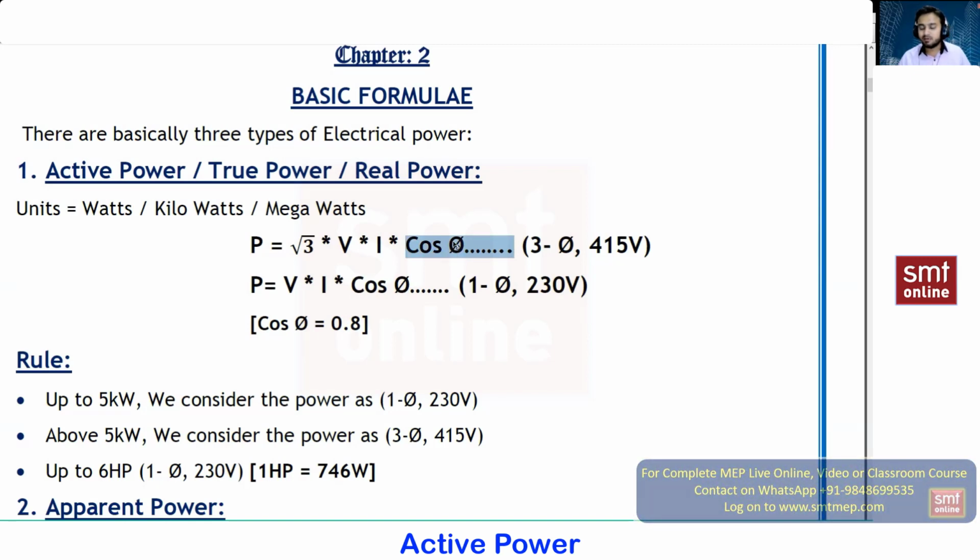This is the basic power factor value which we get from the substation. In my course, I'm going with a power factor of 0.8. If you're working in a metropolitan city, or on good projects, the power factor can also be 0.85. Now talking about the single phase system: for single phase, we have P equal to V I cos phi. There will be no √3 over here.